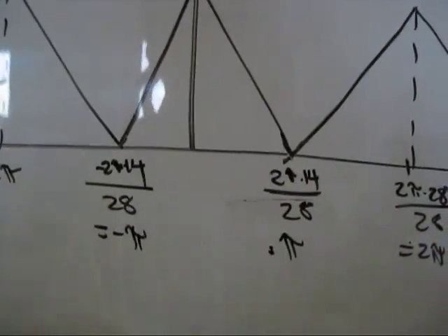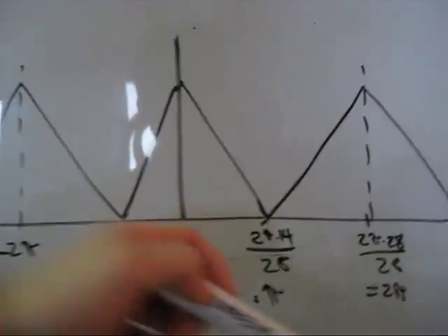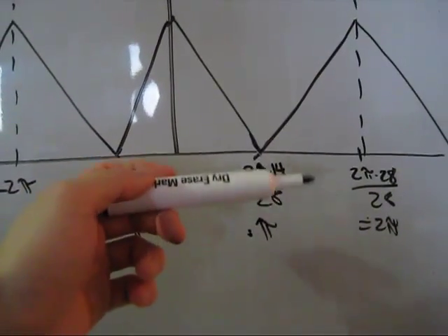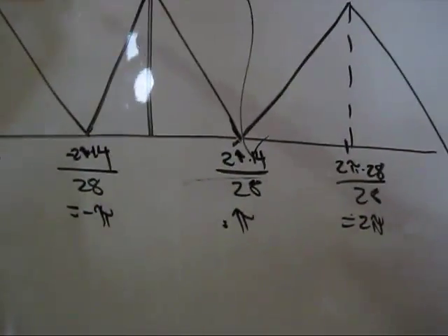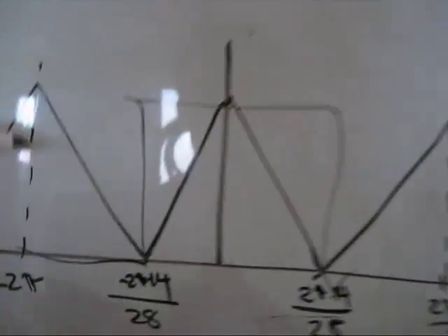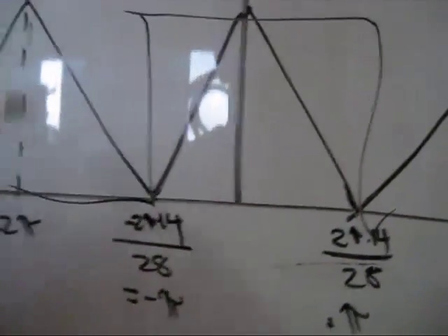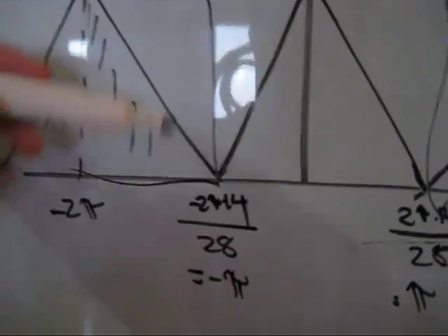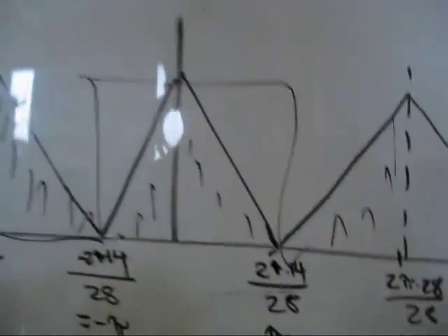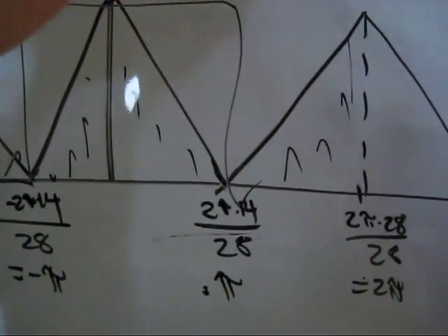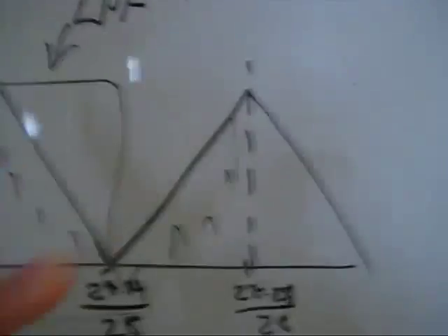So then you could put it back through your digital analog converter, and filter out the high frequency components. Everything that's close to 2 pi and minus 2 pi is all high frequency, and this is all low frequency. So what do you have to do? Low pass filter that, and you would filter that out, and that out.